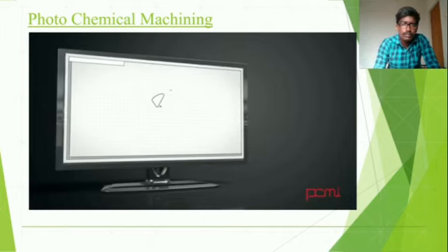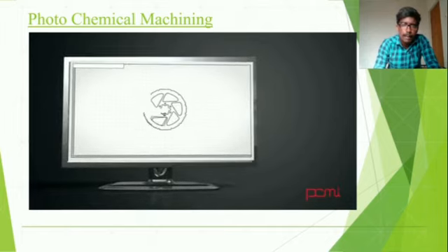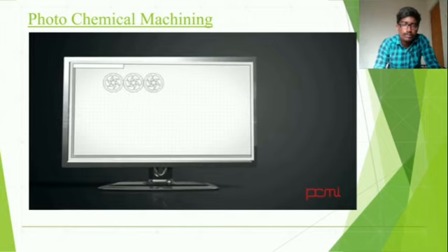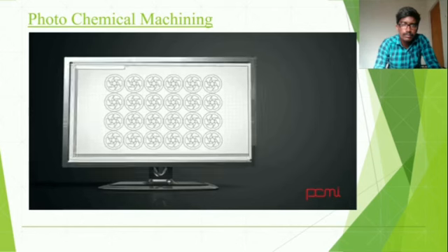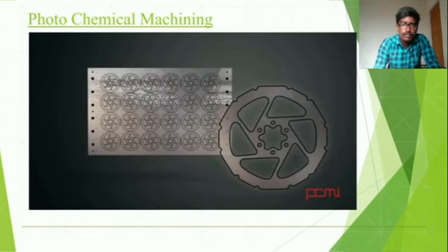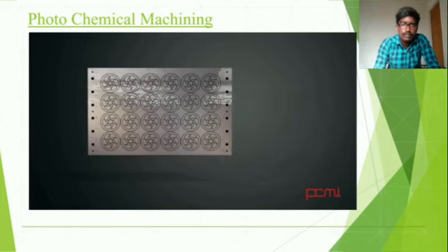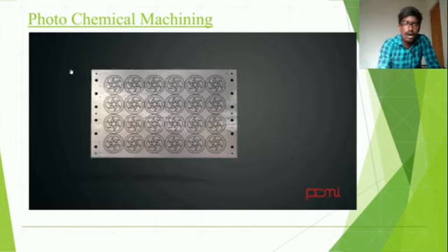The first thing that needs to happen for a part to be chemically etched is for artwork to be generated. Drawings are taken from computer data and photo plotted onto film, creating areas on the film that are either black or clear. Depending on the type of photoresist being used, either the clear areas or the black areas will be the image of the desired part. So it is the artwork generation.